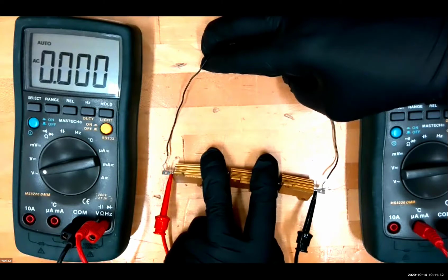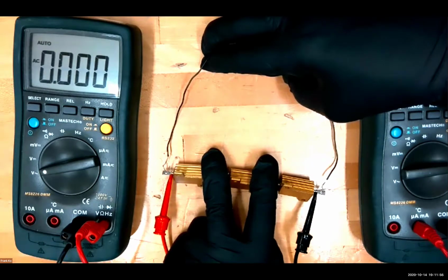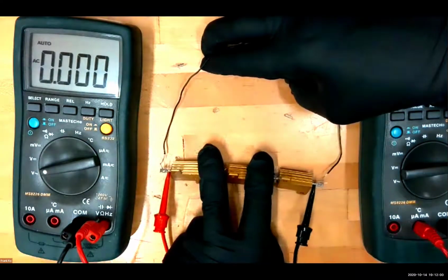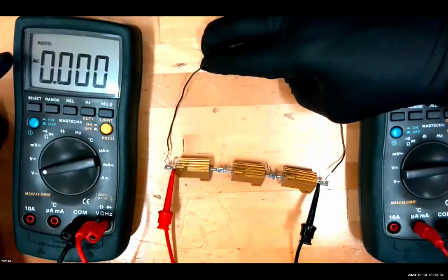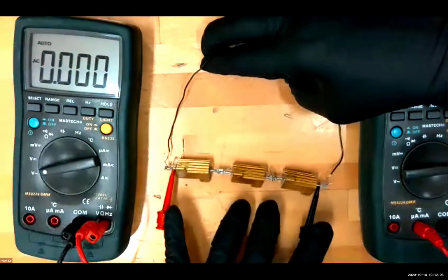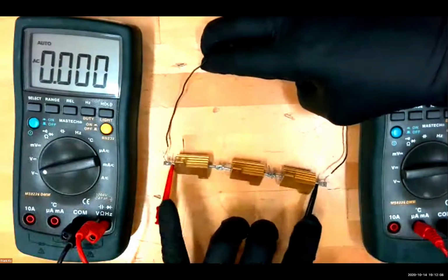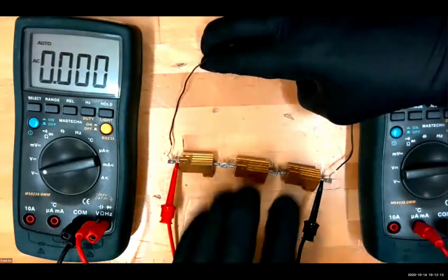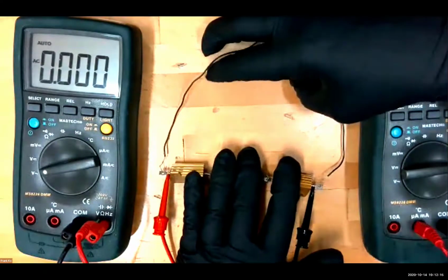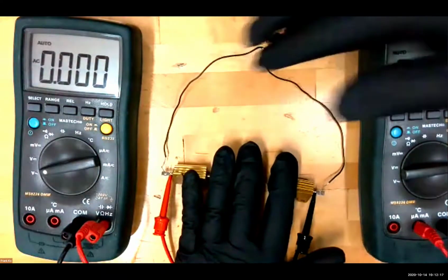Does it not matter because it's AC? Think about it. It doesn't matter because this is AC. Yes, it's going to read a value with no negative sign because this is AC. So it makes no difference which side you put the red. Are we clear on that? All right. Now let's go ahead and bring in the ammeter.